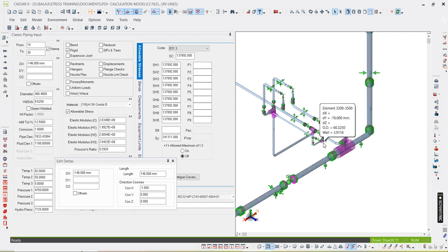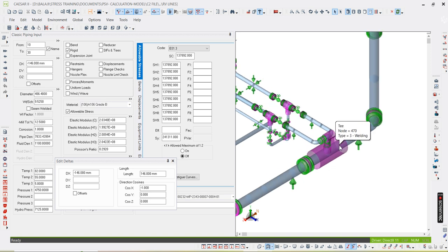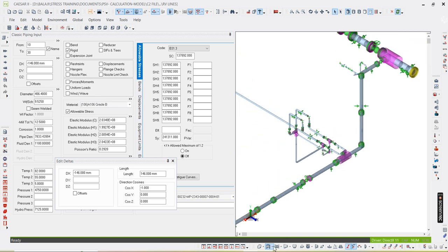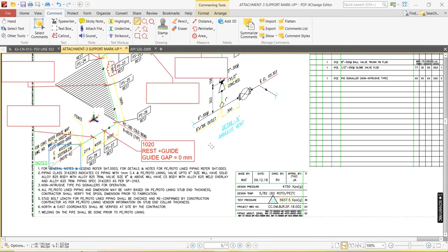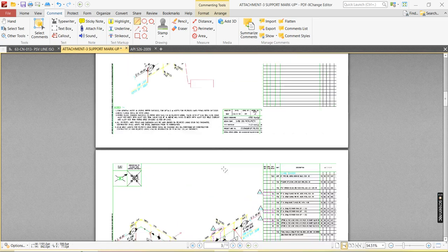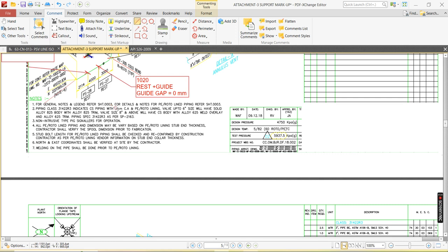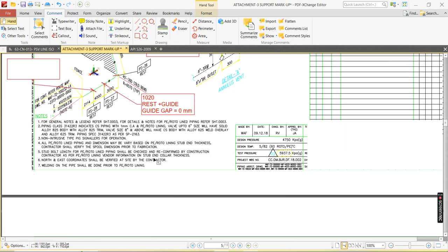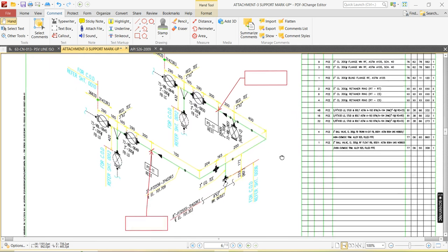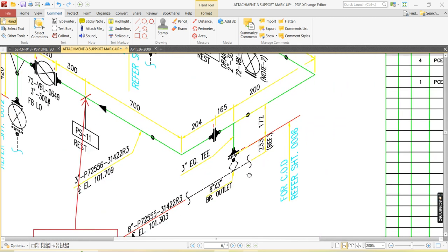If the lines are interconnected, you can easily model because this T has been defined by us. So we need to see where the line is getting connected. Go to this last node number, last sheet, and it is continuing in the next sheet. Yeah, this is the PSV inlet line.